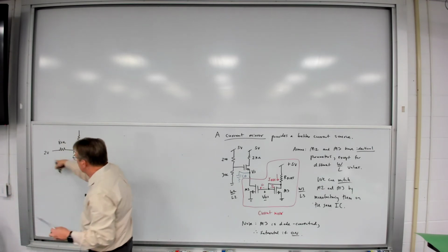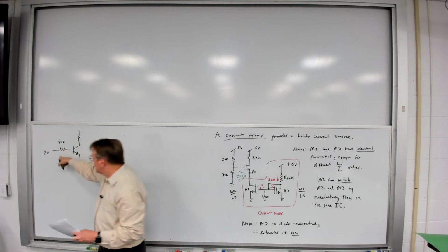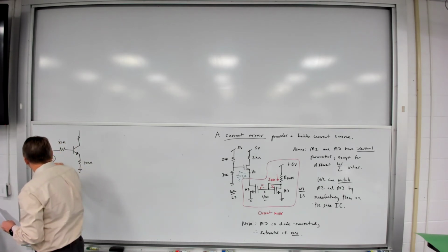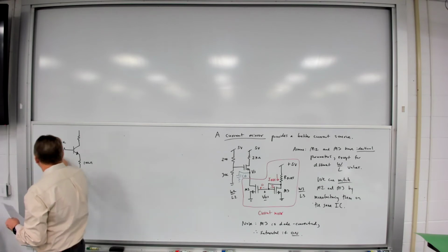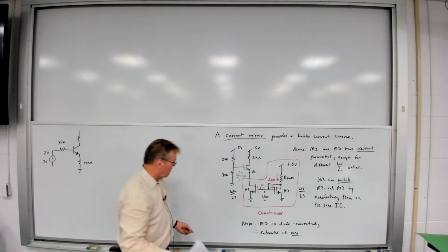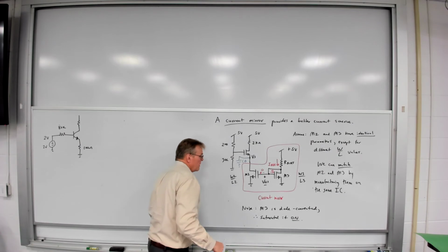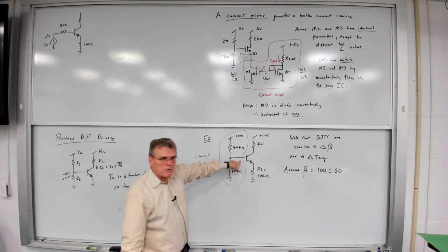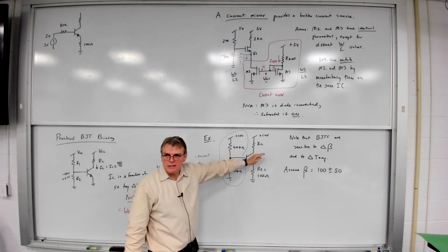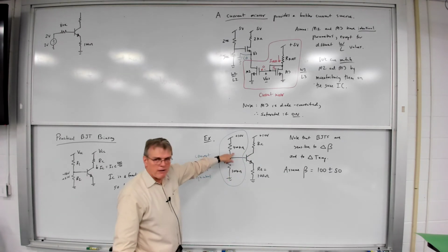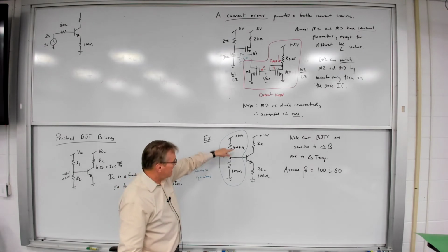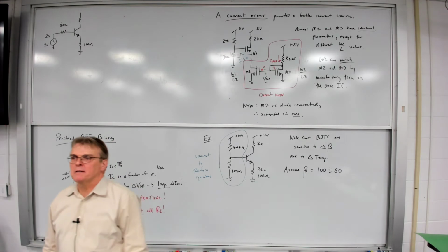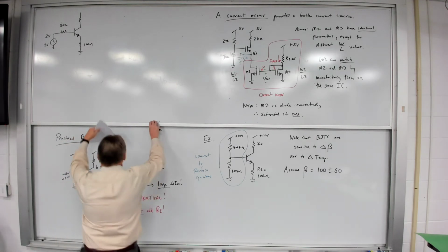Okay, so when I turn my base voltage into its Thevenin equivalent, I wind up with a 2-volt source and an 80K resistor. That 2 volts is just the open circuit voltage here at the base with everything disconnected, 100 over 500 times 10, and then the 80K is 100K in parallel with 400K. So I wind up with this circuit.